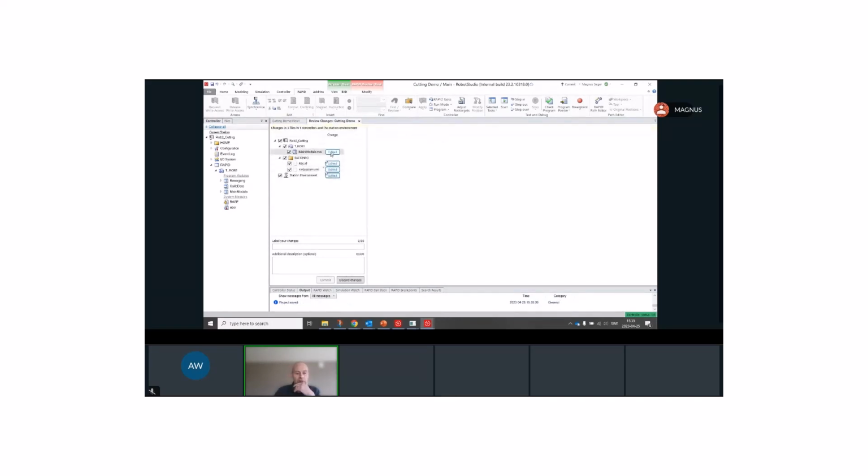And you can see first, of course, I changed the program. And this compares the previous and the current version. In this case, I added a few things to the RAPID program. There are also some changes to the station. There are some date stamps, etc. and so forth. But if I'm happy with this, I can say, hey, I always have to write a comment to have this traceability. So I added wait time and a proc call. Okay.